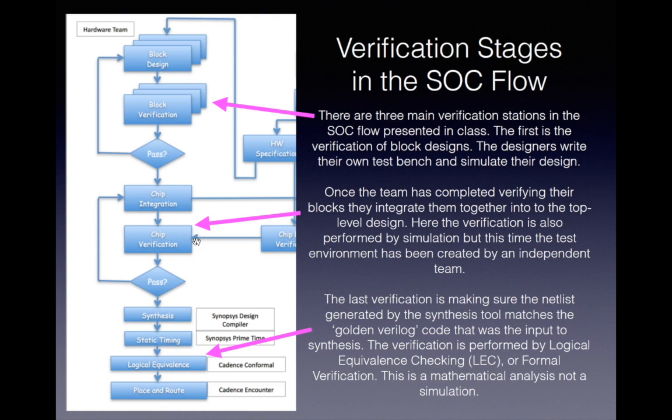In the past, people simulated it, but it turns out to be very time consuming. The methodology we're talking about in this class is the third and final stage of verification: we need to verify that the transformation that has occurred through the synthesis process has not changed the structure of our design, that logically the code is the same.